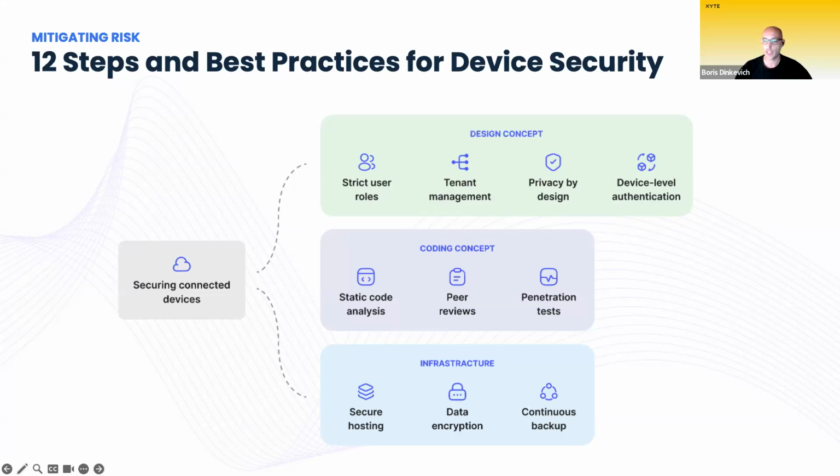The meaning is that when data is sent from your device to the cloud, or from the cloud to the end customer, or through APIs, you want to make sure that it's also encrypted at any part of the way. This prevents man-in-the-middle attacks, as someone might be snooping or even setting up an access point in an internet cafe and having you connect to it by accident. You want to make sure everything's encrypted: TLS, HTTPS, MQTTS. All the protocols have an S at the end for security, and it's strongly recommended to use them, and it's doubly important for devices.